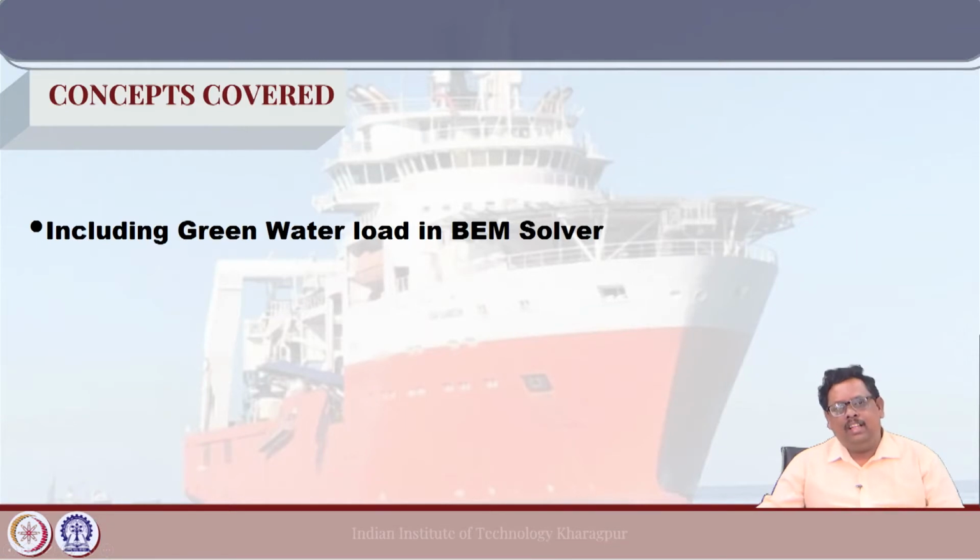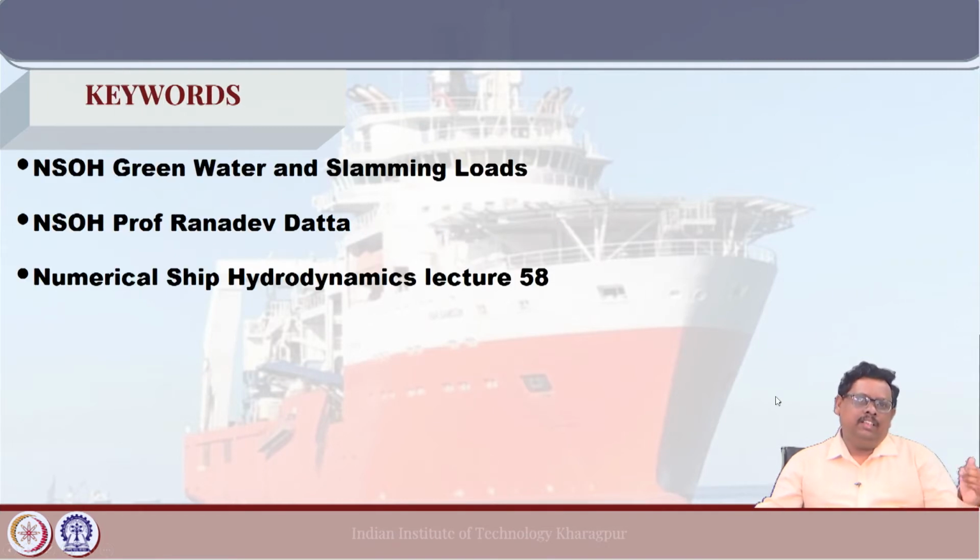Today we are going to discuss how we can incorporate some kind of nonlinear wave loads, for example green water, into the BEM solver. For today's class I selected the impulse response based method as a BEM solver, and there we can incorporate the green water loading. You can take any BEM solver, even the time domain panel method, no problem. But here, for the sake of simplicity, we have taken the IRF based solution.